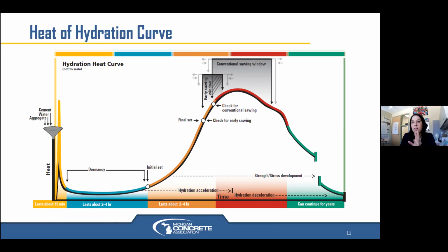Okay, large areas of pavement, saw cut timings become critical. Our thoughts? Absolutely, especially depending on the thickness of your concrete. You have to know the crew, you have to know how quickly they can produce. You need to pour accordingly, making sure your pours aren't so big that you're having trouble getting on the saw cut timing.